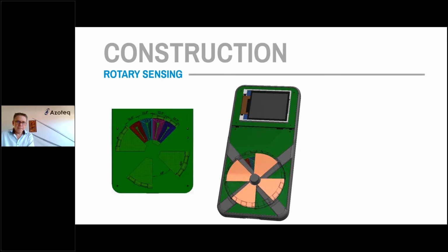This is a 50 millimeter diameter knob, something that is typical for washing machines, laundromats, and dishwashers as a user interface. You can design the coils behind the front panel and have the moving part on the outside, with no need for a shaft or any special O-rings or parts for sealing the moving part off from the electronics. The demo kit in the animation has 16 position precision, working through 4 millimeters of glass.